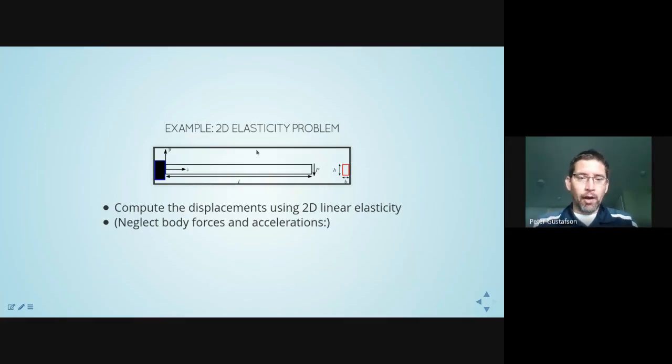We're not going to deal with the third direction. Now, it's worth noting the coordinate system that I've set up here happens to be X, Y, and Z, so that X is out of the plane, Y is vertical, and Z is along the length of the beam. In fact, X is into the plane. I said out, but I should have said in to make sure it's a right-hand coordinate system. And the reason we do this is because many of the equations we're going to develop later for beam theory actually use the beam axis direction as Z. So I'm going to use that here as well.